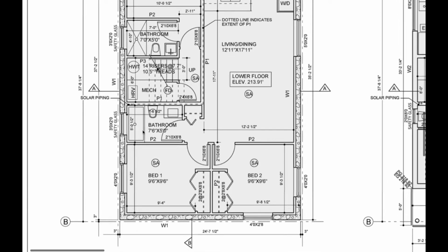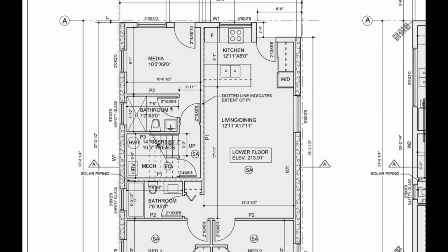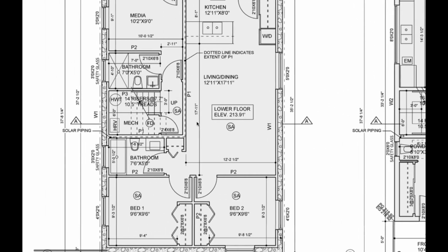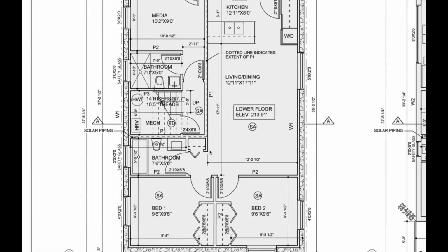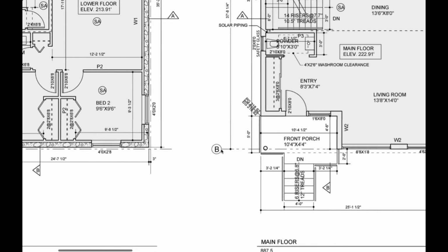Most of these, the joists are going to be running this way, so there's probably going to be some more footings going in here to support these walls down here, because they're not just going to sit on the slab. It's also important to think about your load path in the structural. It's going to tell you what your bearing walls are, but especially around a staircase, you're probably going to see some bearing walls and some more strip footings going in. That's good for the basement.